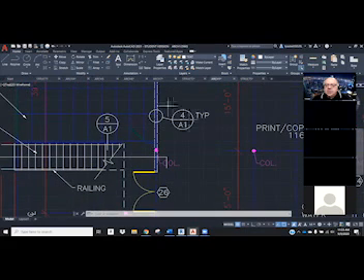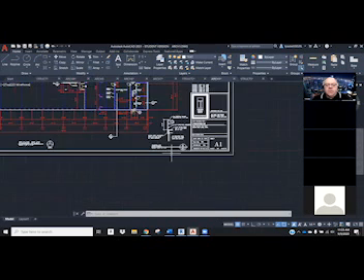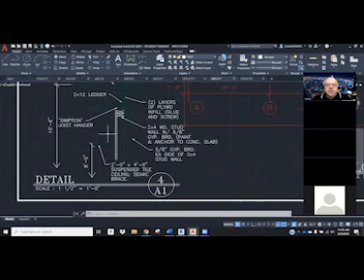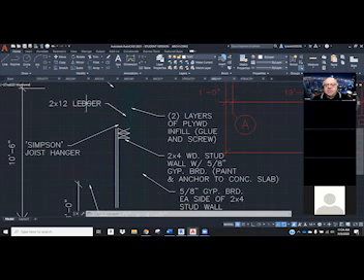Likewise, you need to know what's going on with this wall. This is the detail A4 on sheet A1. Well, we're on sheet A1 right now. That's architectural sheet 1. So detail 4 is over here. And here's information about what makes up that wall. We've got 5/8 chipboard, 2x4 stud. We've got some top plates and a ledger board. You need to be familiar with these if you're doing the commercial projects. Okay? All right, now let's go have some real fun.